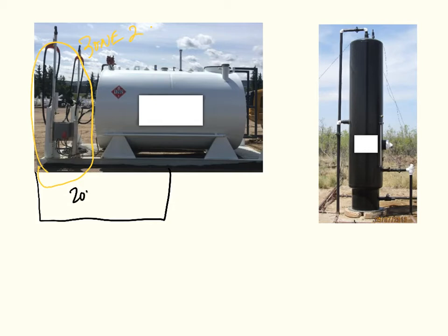This is actually a Zone 1 location because of the hazard that we see with particular liquids like gasoline, where it actually is more dangerous below ground than it is above ground. It's very difficult for air to mix with that gas in order to dilute it to where it's not so dangerous, and so that would be Zone 1.